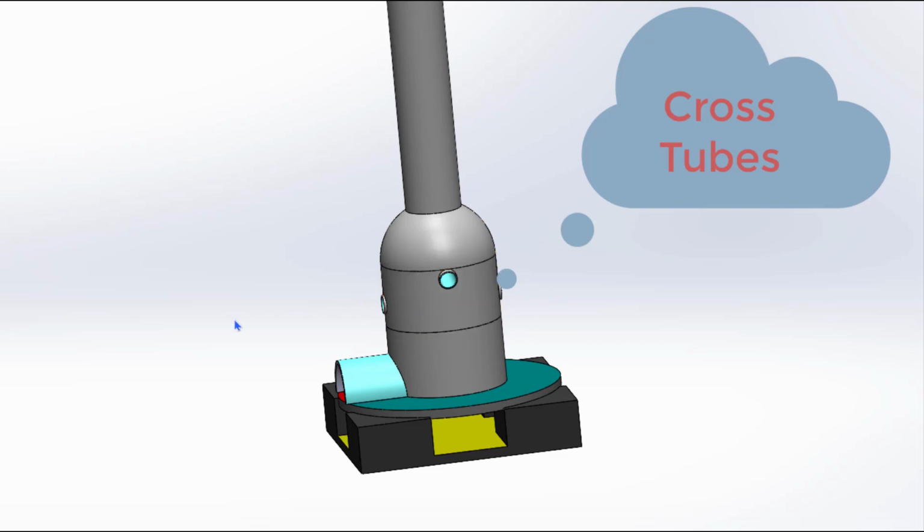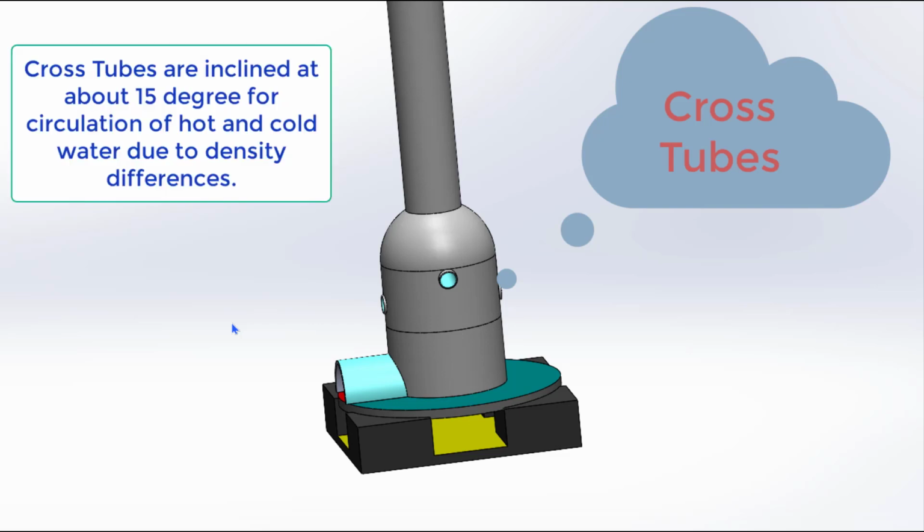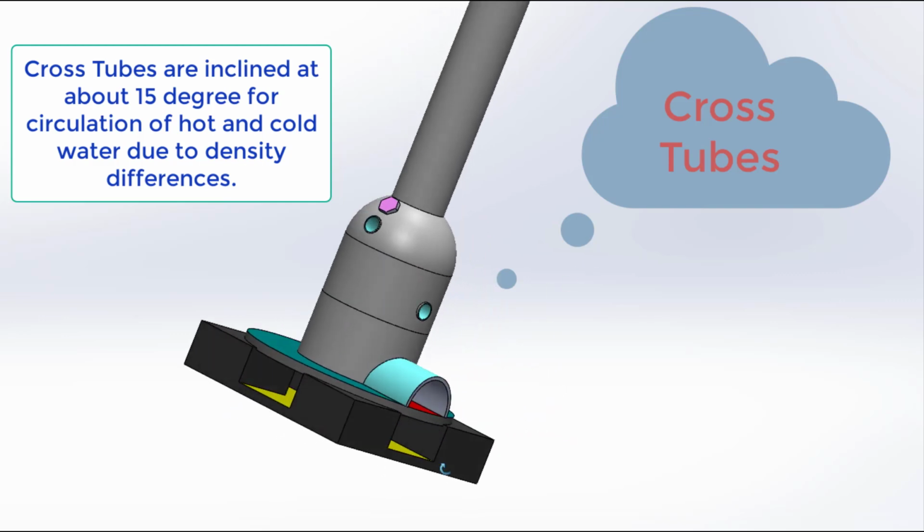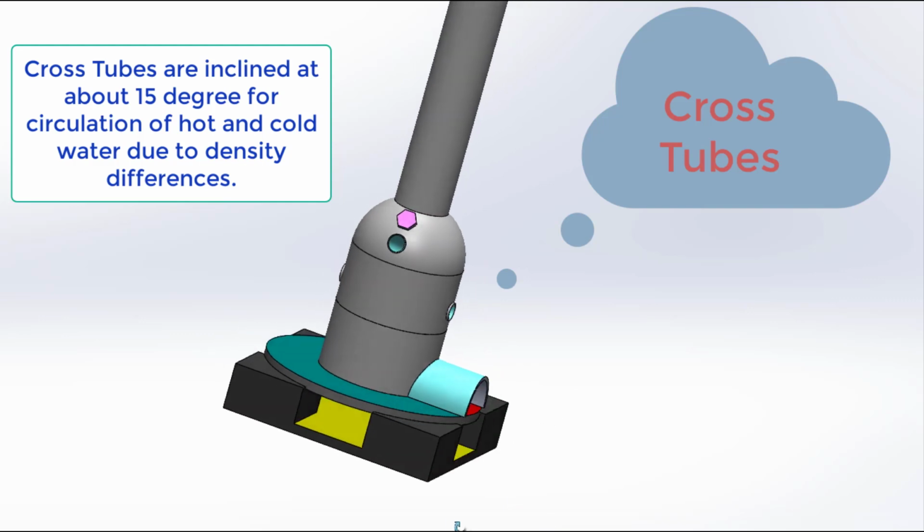the circulation of water. It helps establish a proper convective current during the heating of the water, because the low density water after absorbing the heat will go up, because the water density decreases when it gets heated. So low density particles will go up through these pipes. That way a good convective current is established.